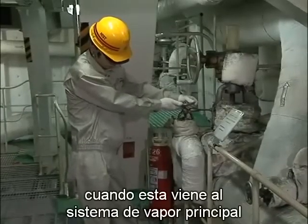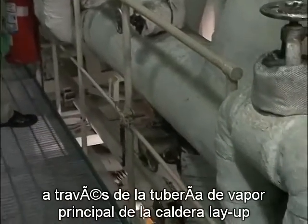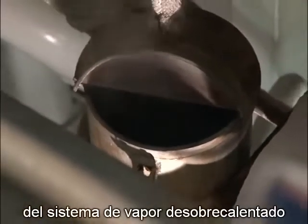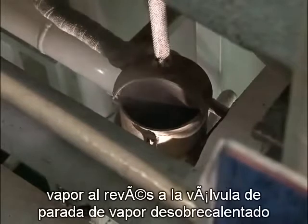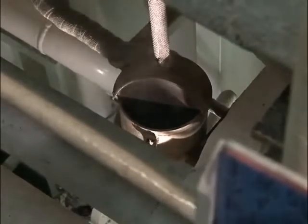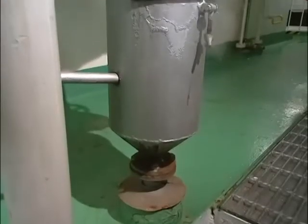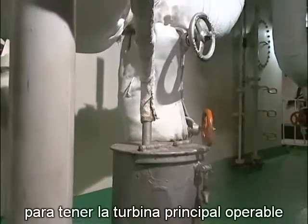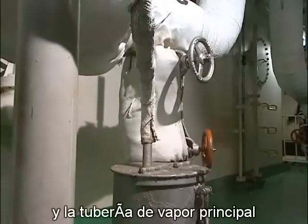When it comes to the main steam system, piping warming up is carried out by flowing superheated steam backwards through the main steam piping of the layup boiler. For the desuperheated steam system, piping warming up is performed by flowing steam backwards to the desuperheated steam stop valve of the layup boiler. Trial run preparation is conducted in this manner to get the main engine turbine operable, after warming up the main engine turbine and the main steam piping.